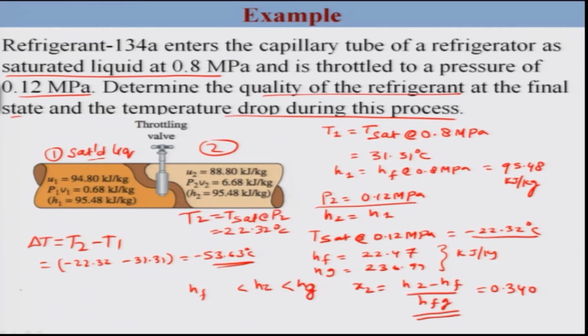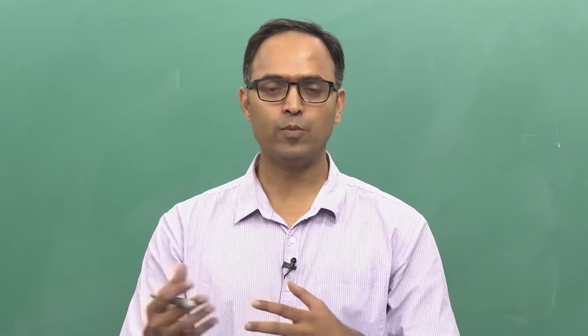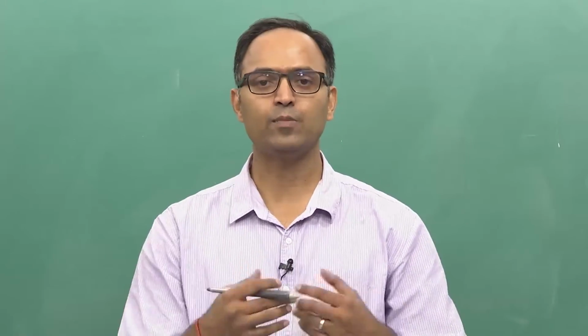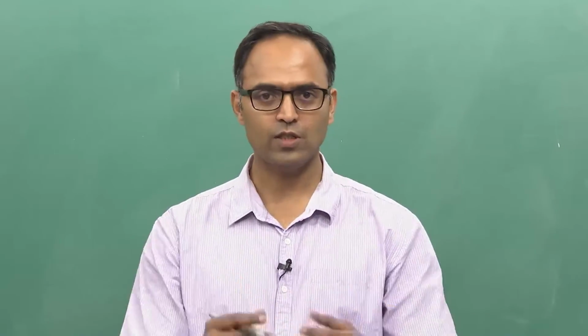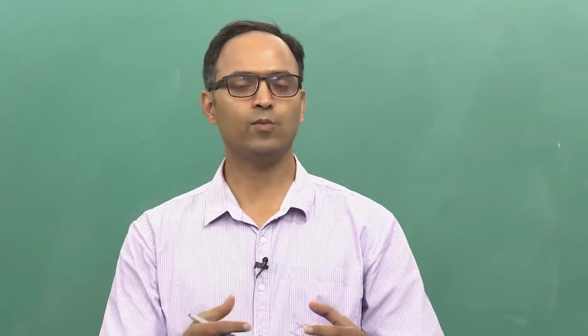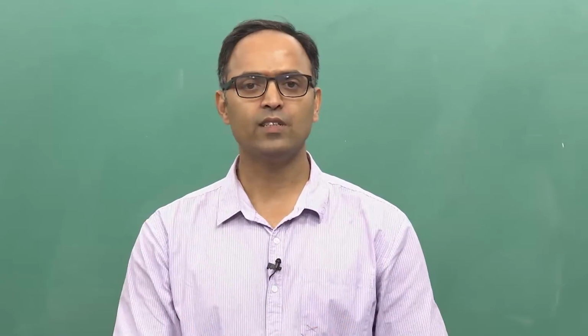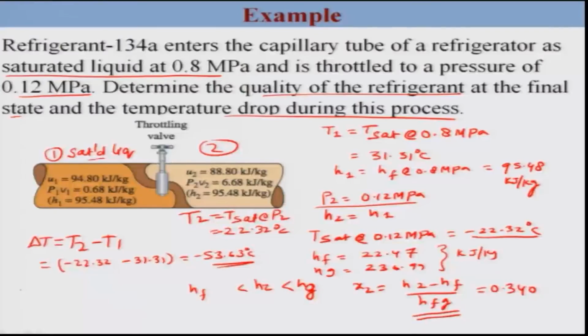So, it is very clear that there is a significant drop in the temperature, and the saturated liquid vaporized. The energy to vaporize, it takes from its own enthalpy. That is quite interesting, because the energy required is not taken from any specific external source, but it changes its own state through this particular capillary tube and makes use of it for vaporizing from a saturated liquid to saturated vapor liquid conditions.